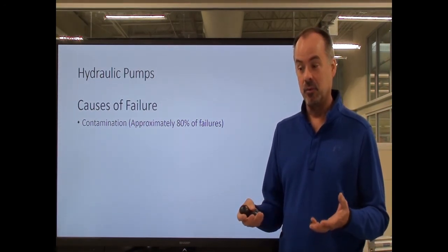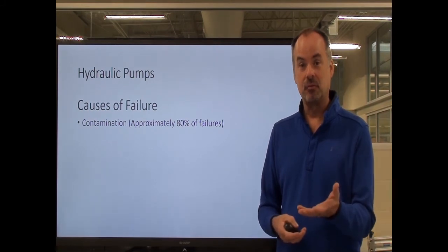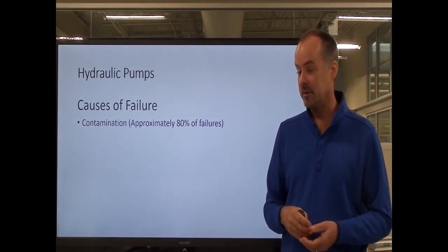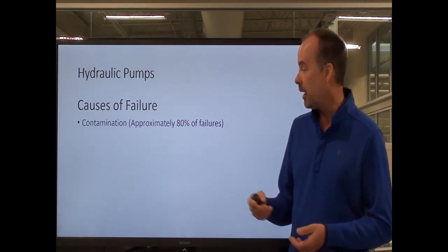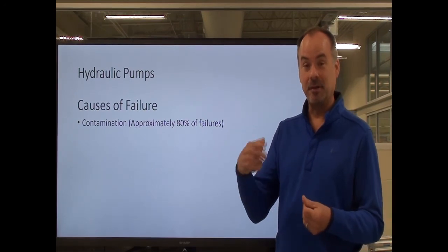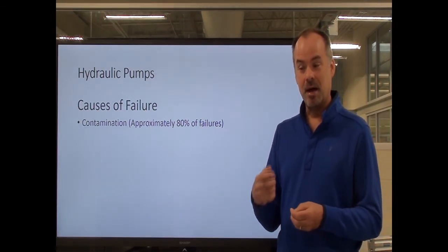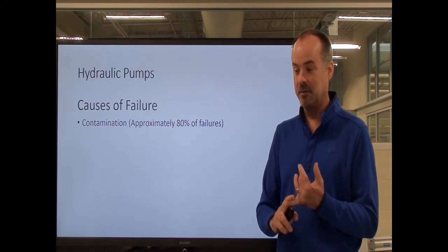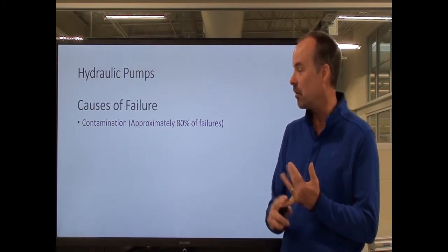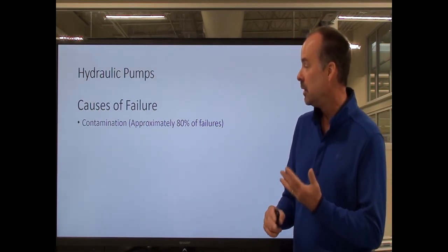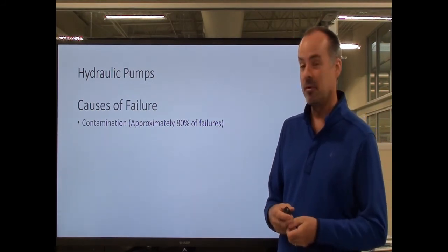If it's not filtered well, maybe your filter fails, it pulls that contamination into the pump and will cause erosion. It'll really eat itself up, and it'll start bypassing inside, and you'll start noticing it can't produce the same amount of flow that it did before. Pressure might start dropping.